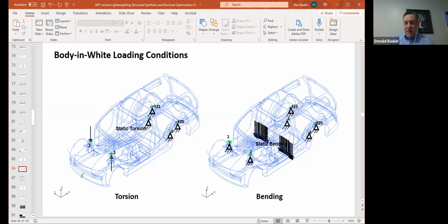Bending load is also very important. Bending load has more to do with the comfort of the vehicle going down the road and less to do with handling. This is because when you hit a big bump in the road, you don't want the body structure to start oscillating. You want it to hit the bump and then stop, and not flex back and forth a bunch of times. The stiffer the body structure is in bending, the less chance that you hit a bump, it hits some frequency, and starts jiggling around. Customers can feel that, or sometimes hear it, and they don't like that, and then they'll rate a car as being loud or uncomfortable.